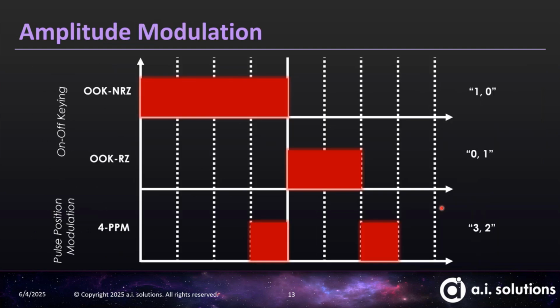Okay, so another thing that Chris alluded to, modulation is an important parameter in an optical link. In optical communications, especially deep space optical communications, modulation of the signal tends to not be too fancy. In fact, a lot of them are essentially just blinking the laser, and so that's amplitude modulation. There are a number of different ways to blink a laser, as it turns out. But a few of the commonly used ones are something that's just called on-off keying.